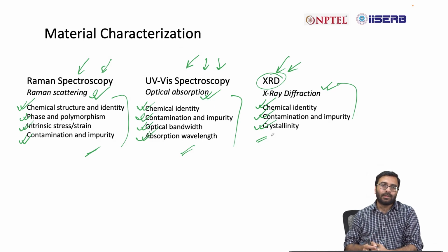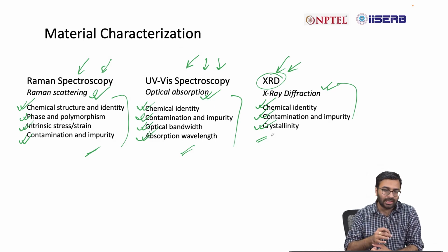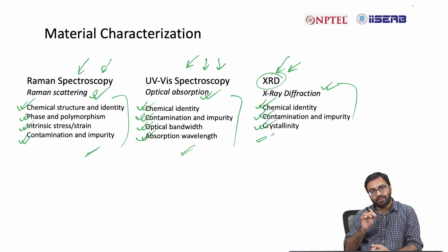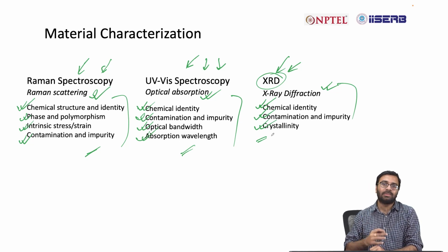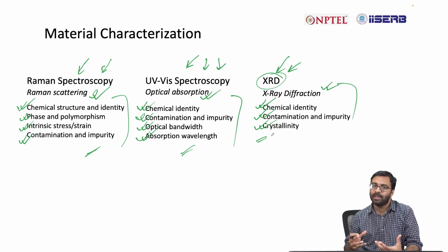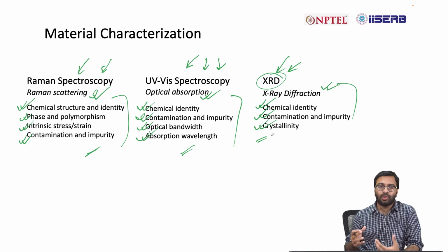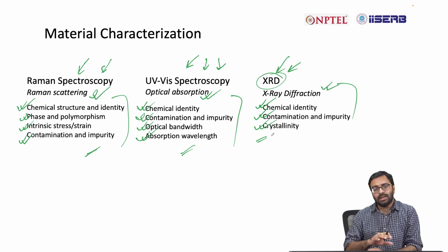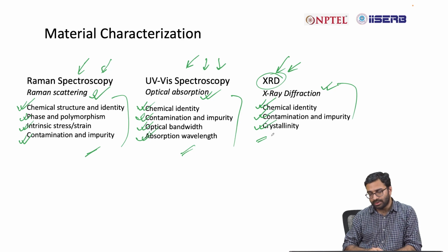However, equipment is decided based on the phenomena or physics associated with it. For example, if it is a resistive sensor, a digital multimeter should be sufficient. A high resolution digital multimeter should be sufficient. If it is a capacitive sensor, you may need an LCR meter, and so on and so forth. So these are the other characterization techniques associated with sensor technologies.